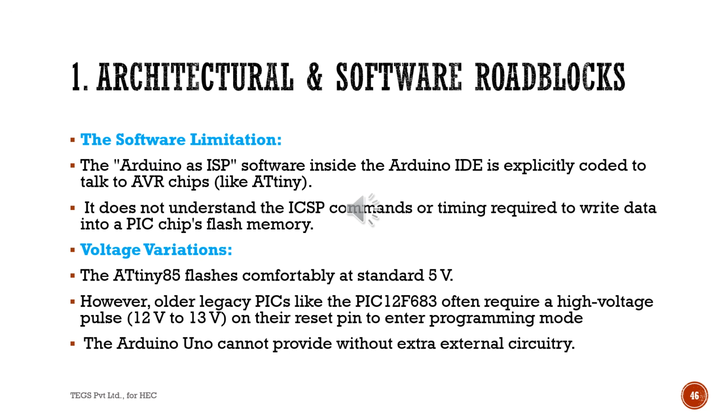Voltage variation. The ATtiny flashes comfortably at standard 5 volts. However, older legacy PICs like the PIC 12F683 often require high voltage pulses, 12 volts to 13 volts, on the reset pin to enter programming mode. The Arduino Uno cannot provide such voltage without external circuitry.